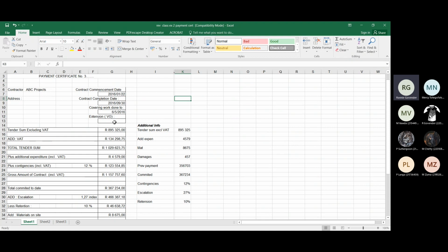But let's say, for argument's sake, now you say to move the sewer pipe is going to cost 200,000, and he thinks, hey, that's a bit too much, it's not market related. Then he'll probably come out on site, and he'll have to look at why you say it's 200 or whatever the case, and then he'll authorize, and you will agree on a price, which normally would be a written agreement. And then, the written agreement is in the form of a variation order. Variation order means, that's why it's called a VO, meaning that you're going to vary from the original contract that you signed. And nothing formal, it doesn't have to go through tender board and all that.